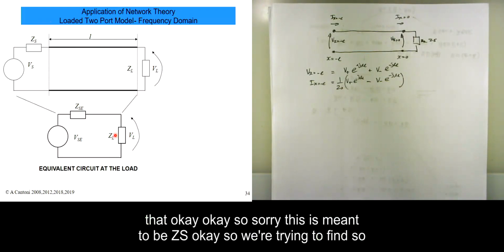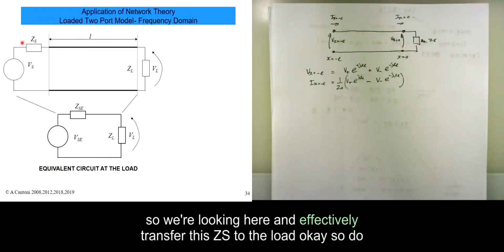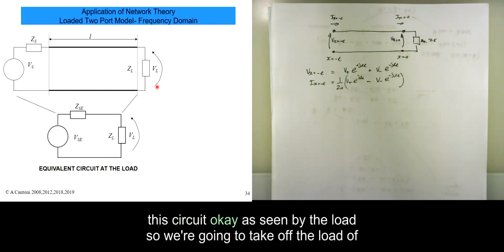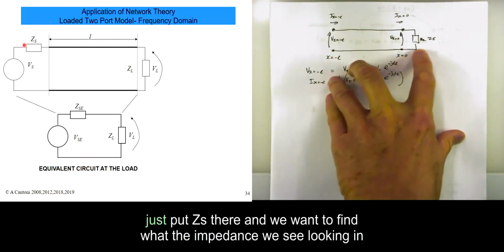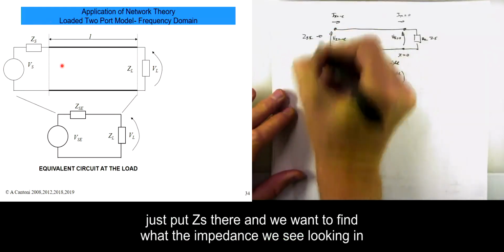Sorry, this is meant to be ZS. So we want to find the Thevenin equivalent impedance. So we want to look in here and effectively transfer this ZS to the load. So we just try and get the Thevenin equivalent of this circuit as seen by the load. So we're going to take off the load, of course, and remove the independent voltage source, VS, and just put ZS there, and we want to find what impedance we see looking in.